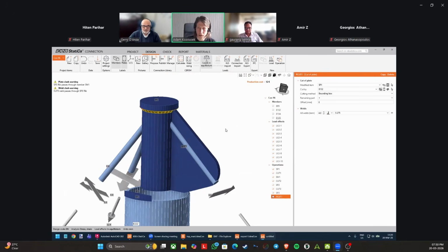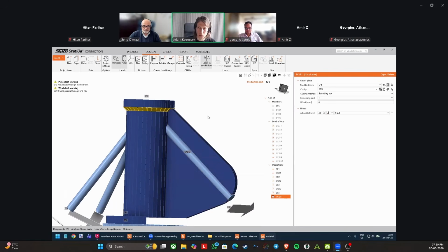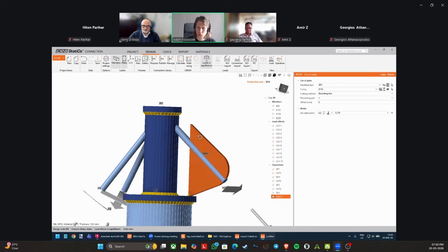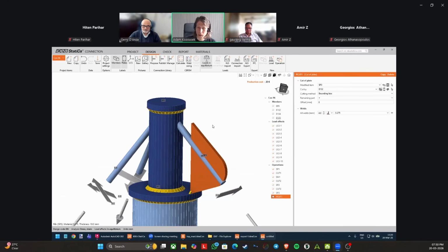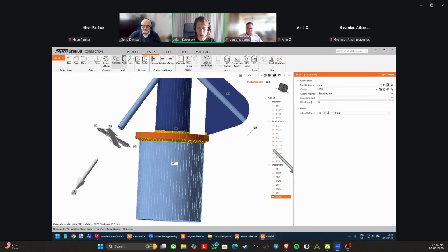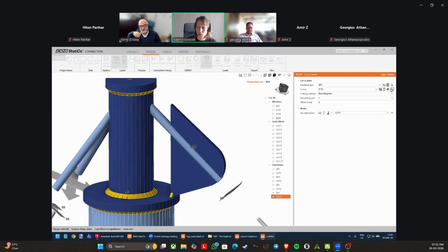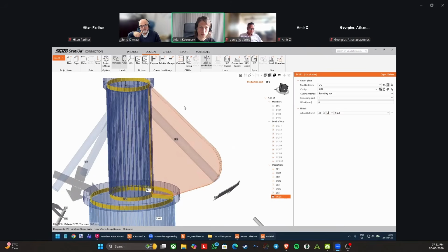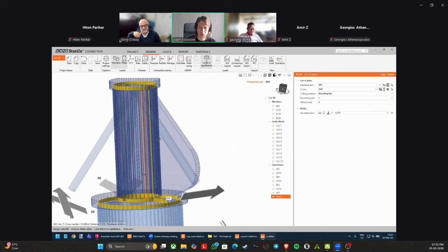Yes, yes, exactly. So what I do is I have this cut of plate operation. So again, I choose which plate I want to cut. It is this one, the SP3. And I choose what it chose automatically, the member B102. So you see it's cut on the line, but this is of course wrong. So simply switch this like this, okay? So now if I go to transparent, you can see it looks like this.